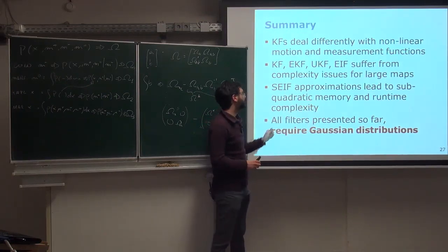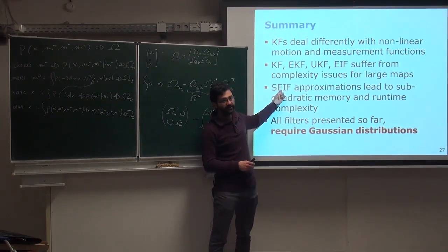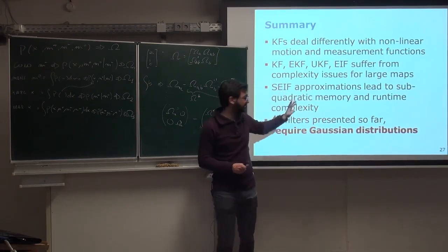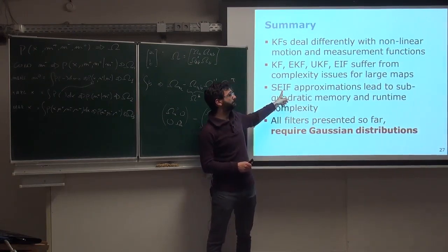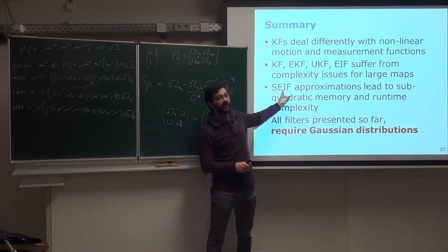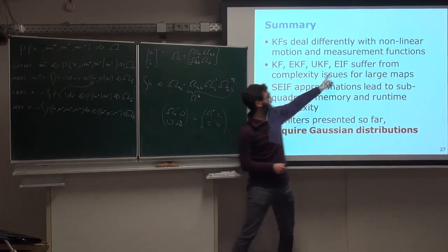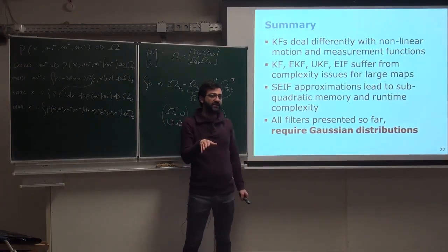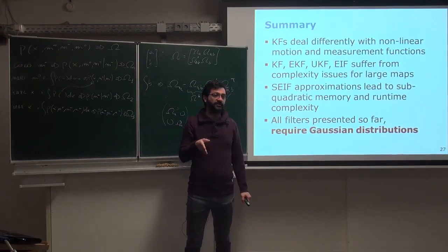There is one small twist. There is a version of the sparse extended information filter, which I believe is called the sparse extended delayed state filter or something like that, where you show that if you're having a full SLAM problem, so if you apply an information filter on a full SLAM problem, the sparsification is actually exact and is not an approximation any longer.